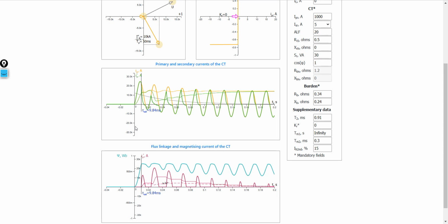As I mentioned a moment ago, the pickup reliability ratio is equal to 2, which means that the setting of the overcurrent protection is only half the amplitude of the short circuit current. I said amplitude because in this case it doesn't really matter. We can multiply the pickup RMS value by the square root of 2 and then continue working with amplitude values. So the pickup setting value looks something like this.